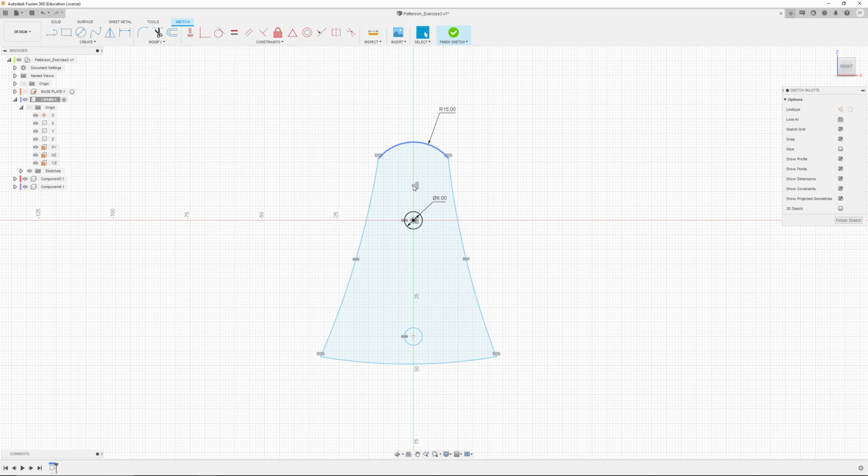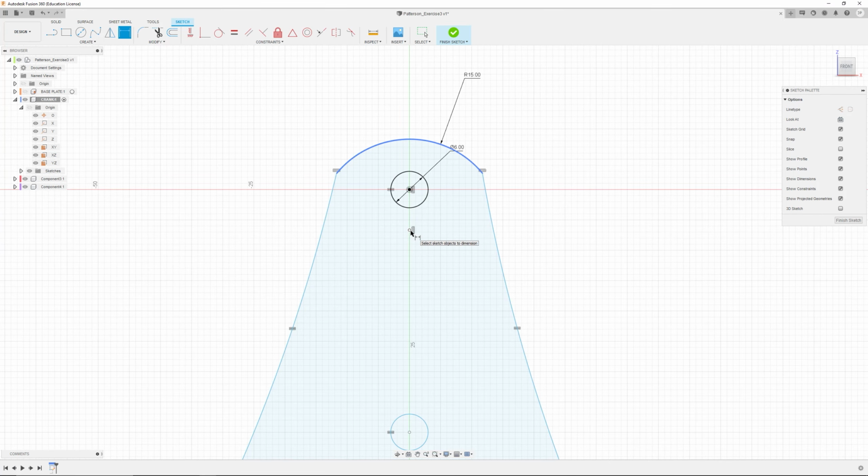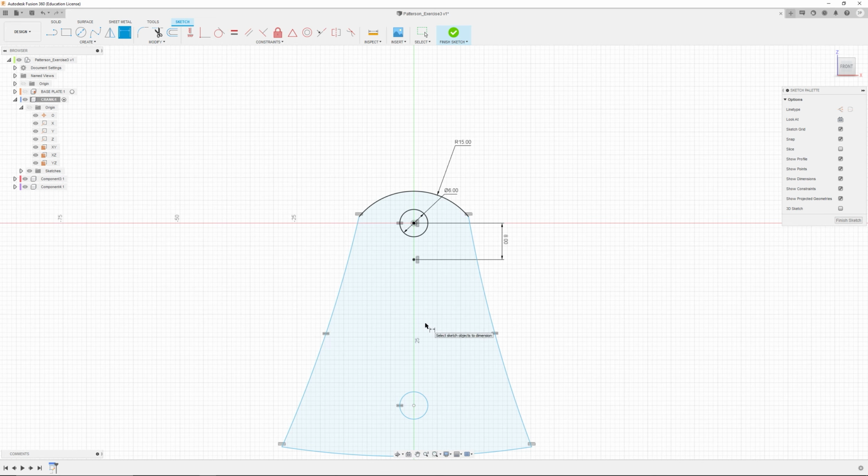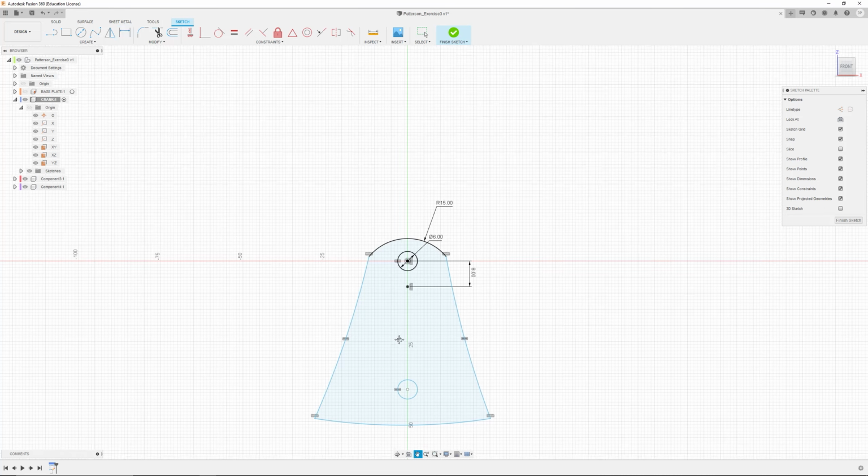And it looks like the center point of this on the drawing is actually going to be located under this. You will notice on the drawing that it is marked by just a little plus sign with a dimension. And the reason I chose this as the origin is because everything is dimensioned off of this point in the drawing. So I want to mimic that in my sketch here. Okay.